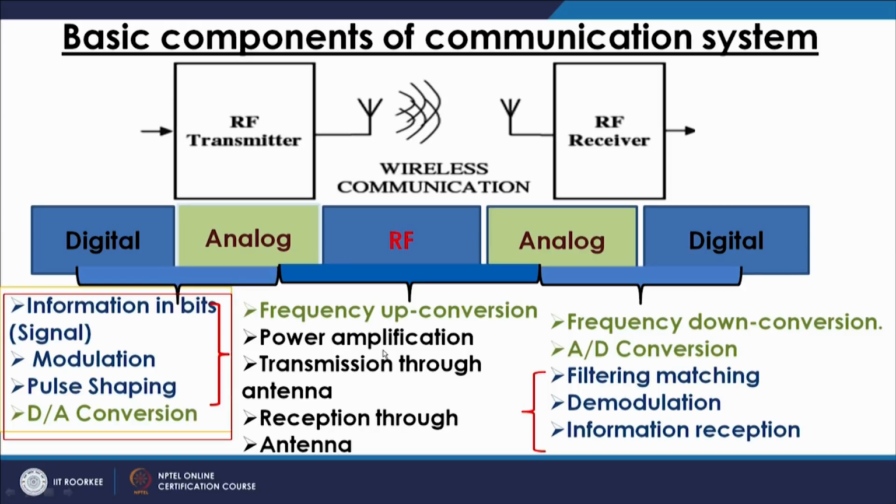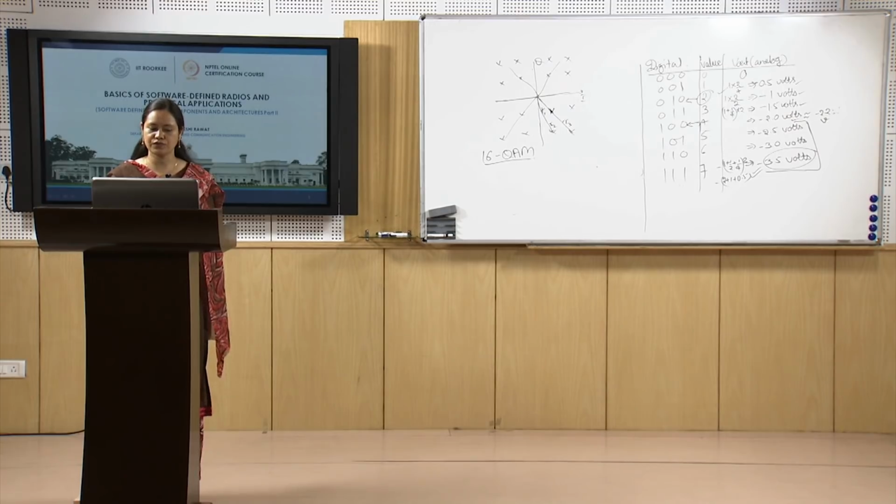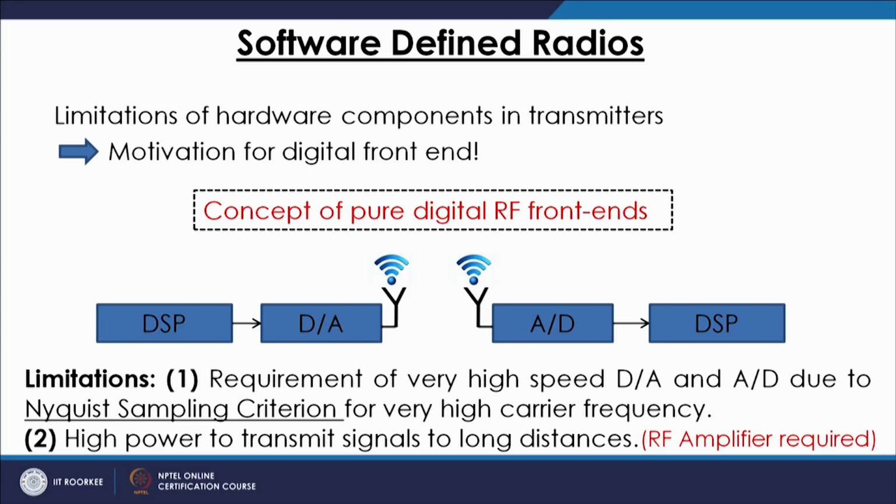As opposed to analog system, if we can have a complete digital system, it can be more flexible. If your scenario changes, you can just change the coefficients and you will have a better precise solution there. It is reconfigurable in nature. So whenever your incoming signal changes or your channel condition changes, you can reconfigure it. Even if your frequency changes, in the analog domain you cannot do it because you designed for that frequency. In digital domain, you can simply use the new frequency, you can define it like that. So of course, software defined radio solutions are better than the analog components.